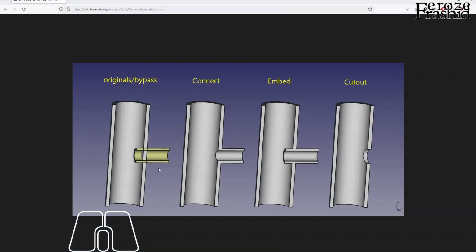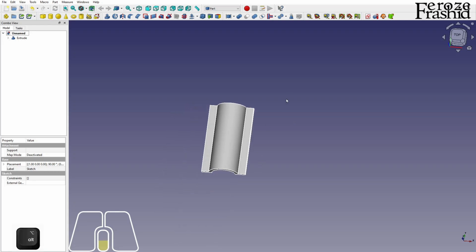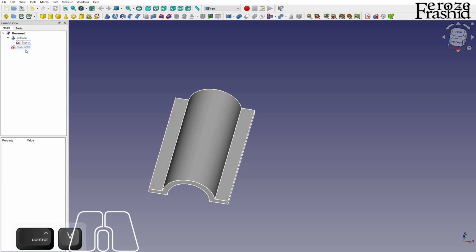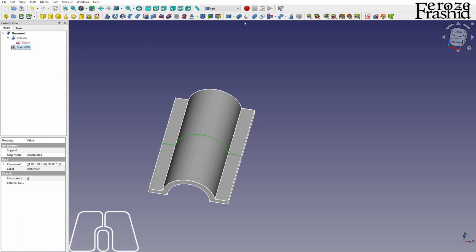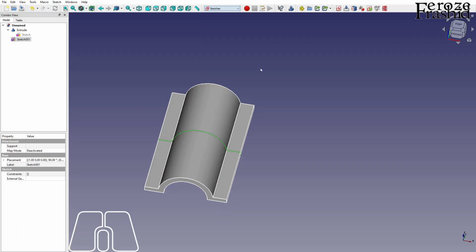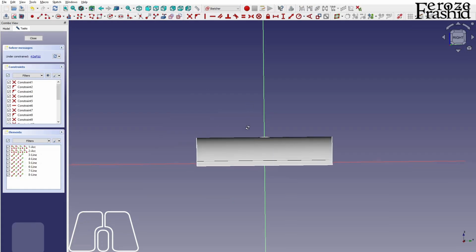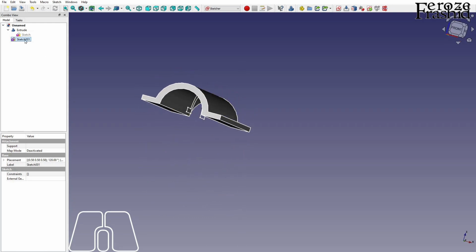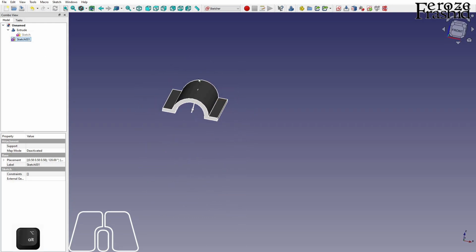And what we have next is another similar kind of thing. I will make it simple and I won't be making it a different sketch. I'll keep the same sketch. Okay, copy that, paste it over. What I want to do is reorient this sketch on a different plane. It was on the XZ plane, I want to place this on the YZ plane now and hit OK. So there is my new sketch that I copied and pasted, and now it is reoriented.